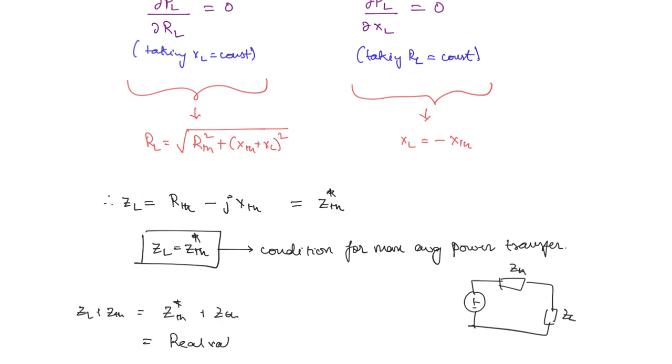The imaginary part is going to get cancelled. Okay. So that means there is no reactance. So for purely resistive circuits, you are going to have the maximum power factor, right? Cos theta is going to be maximum for purely resistive circuits. Okay. So this is something that you can get from normal common sense as well. But this is the mathematical proof.